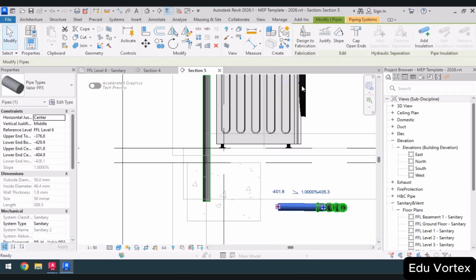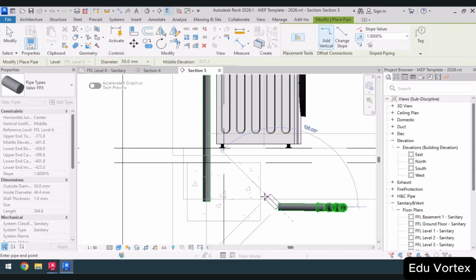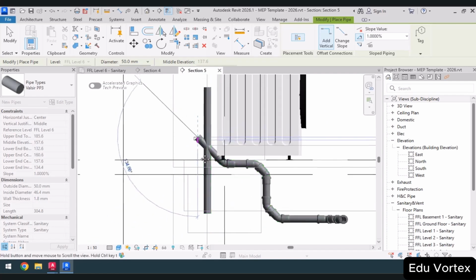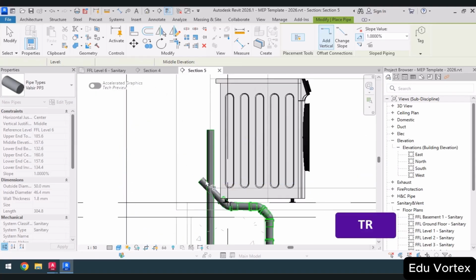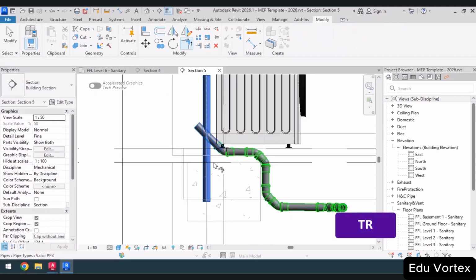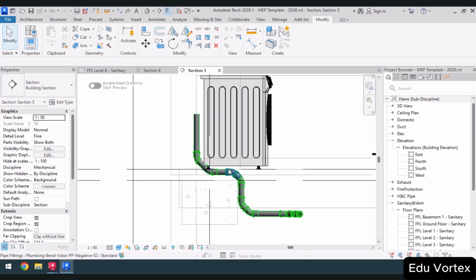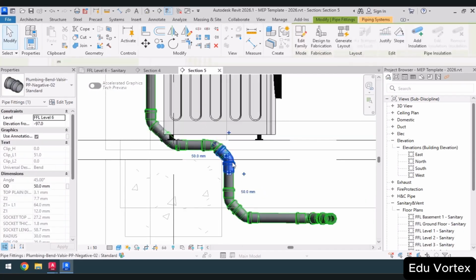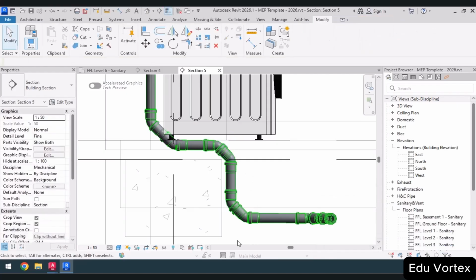So right click and I will drop it at a 45-degree angle upwards. Then again at another 45-degree angle. Now another one. So I can use the trim command TR to connect these two together. We had to draw a line here to bypass the beam, and I will bring it forward until it gives me an error message.